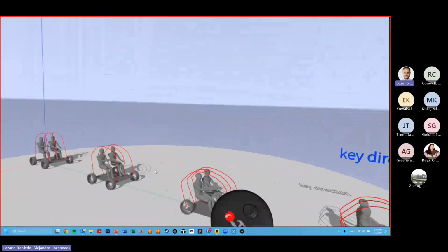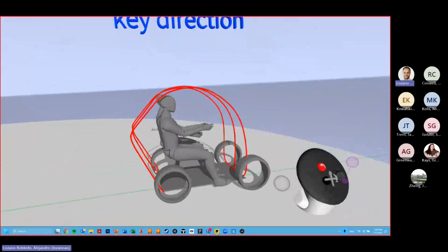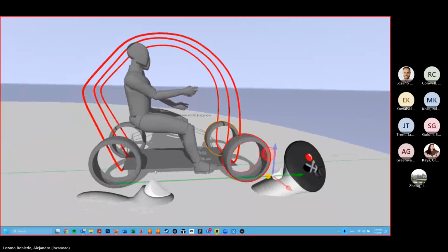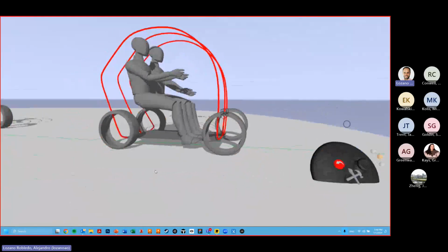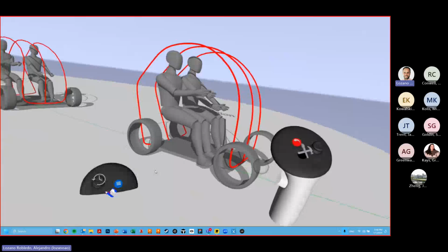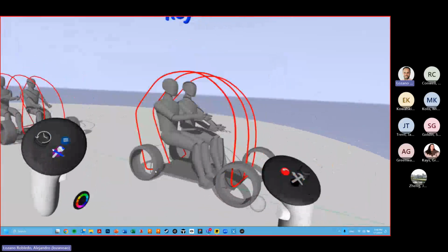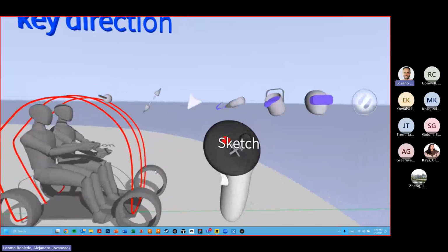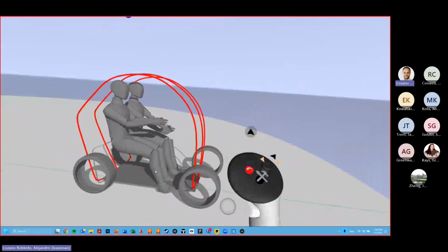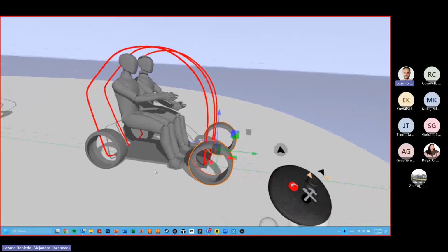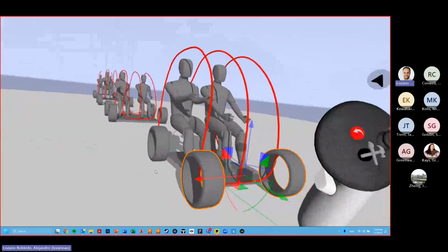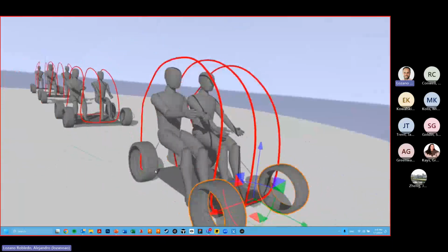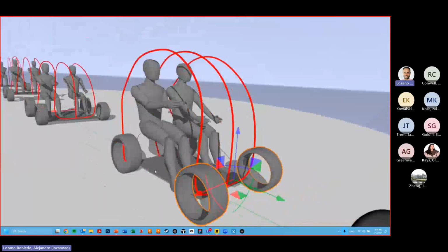Basically what I'm showing in my file is this one is my key direction that I want to evolve a little bit more. There are a few things with it. For example, this wheel still feels a little too big. One trick I can show you from the new update is if I click on my tools, I can choose selection. What this does is it brings an arrow. If I click on any object, it brings this menu that you will recognize from Keyshot. This is for moving, rotating, and scaling. This is the best and most accurate way that I recommend to move, scale, or rotate things.